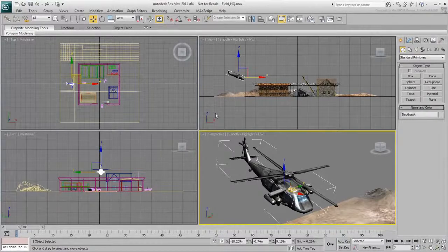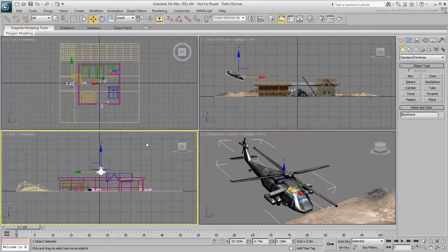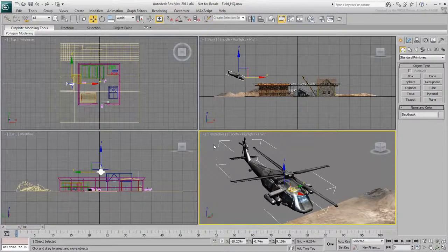In part 2 of this movie, we take a look at the coordinate systems. When you transform objects in a scene, it's important to understand some of the more valuable coordinate systems that are a part of 3ds Max. The base coordinate system is world, where the x, y, z orientations remain constant. This means no matter which viewport is active, the x, y, and z axes do not change, and the z-axis is vertical.